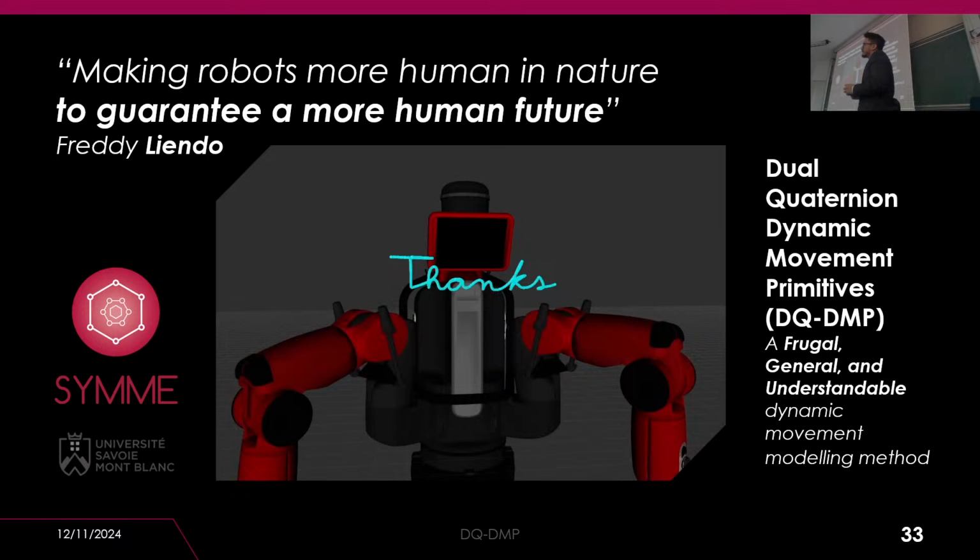So when you throw something, it also matters when you release the object. When you are training the robotic arm, how did you make sure that you also teach when to release the object? Right. Not only did I have the buttons on the arm, because it is equipped with buttons to interact with the robot, configured to indicate where, from my experience, the ball will be released, but also within the 30 minutes or so of training, I curated the movement so that the goal value, the goal pose, the point of release, would be the last value.